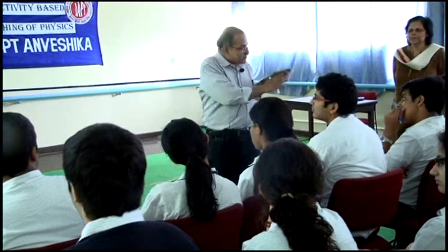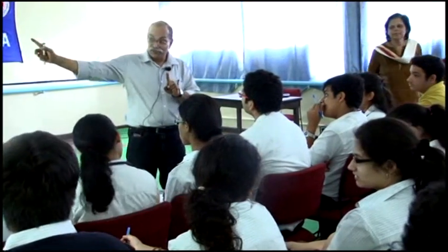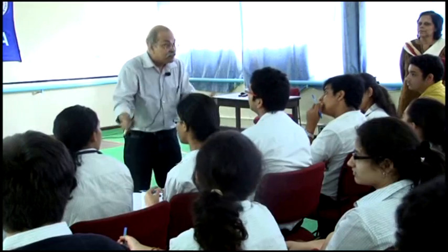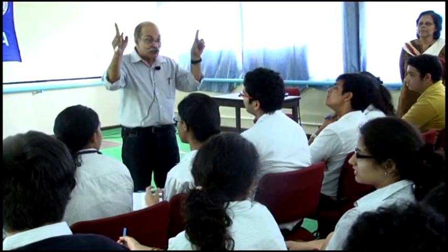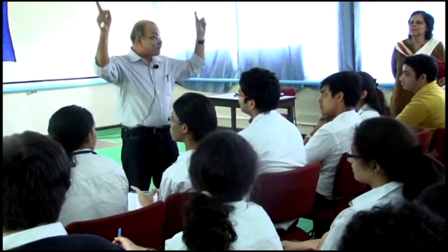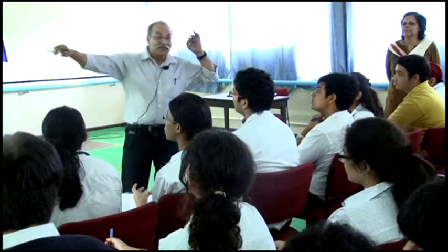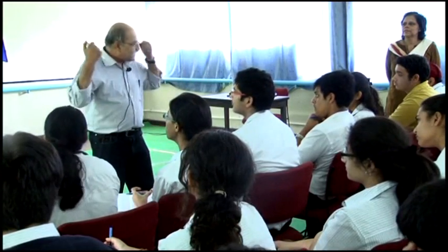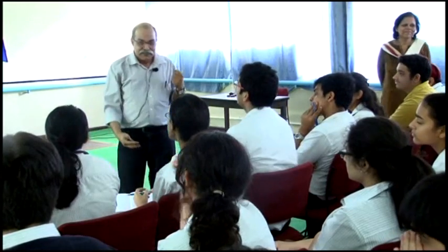I can also analyze what happens to the hinge, but at this moment I am writing all the forces only on the door. I am looking at the equilibrium of the door. The total force on the door should be 0. The total horizontal force on the door should be 0. Total vertical force on the door should be 0. Total perpendicular z direction should be 0. Total torque on the door should be 0. The single point agenda in my charter is the door.